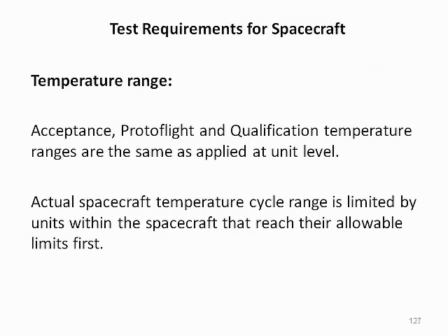As was the case at the unit and subsystem levels, spacecraft level tests have specific requirements that are typically levied by the customer. The goal is usually to reach the same acceptance, protoflight, and qualification temperature ranges that were applied at the unit level, but the actual spacecraft temperature cycle range is usually limited by units within the spacecraft that reach their allowable limits first.